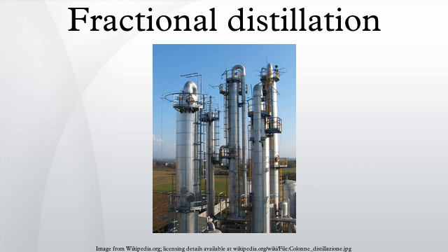Industrial distillation. Fractional distillation is the most common form of separation technology used in petroleum refineries, petrochemical and chemical plants, natural gas processing and cryogenic air separation plants. In most cases, the distillation is operated at a continuous steady state. New feed is always being added to the distillation column and products are always being removed. Unless the process is disturbed due to changes in feed, heat, ambient temperature, or condensing, the amount of feed being added and the amount of product being removed are normally equal. This is known as continuous, steady-state fractional distillation.